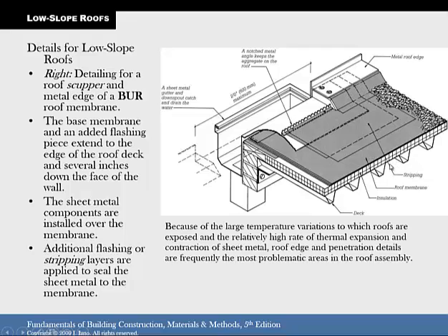Then you got stripping, it's called, or flashing, I think is what I would call it. And then there's flashing here, and then that overlays that. All these different overlaying areas, and you just got to think about where the water's going to run so it never goes underneath those. And then this water will run over here and down the drain.